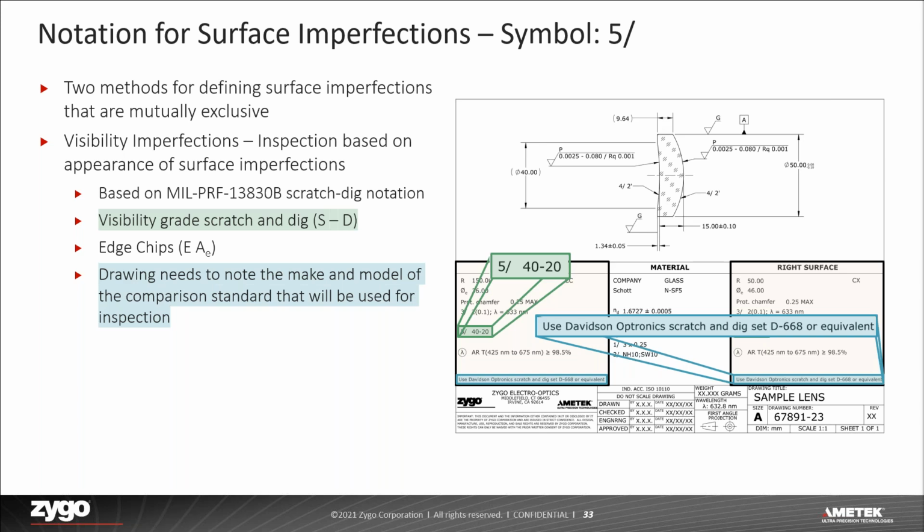As an important note, it's necessary to state the make and model of the comparison standard that you will use. This is to ensure that both the fabricator and the end customer are in an understanding of the standard to reference the surface imperfection against.